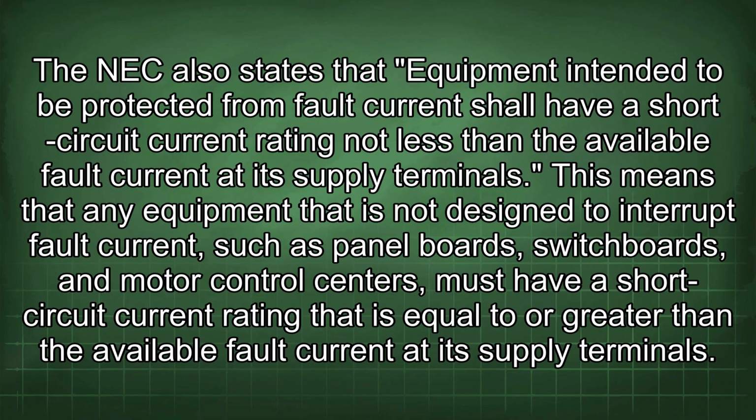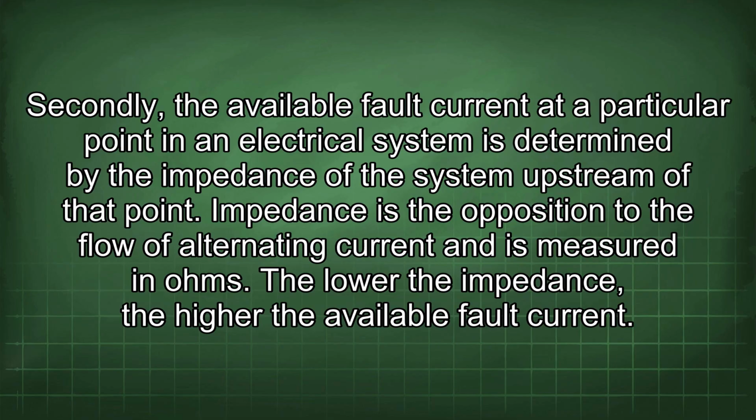This means that any equipment that is not designed to interrupt fault current, such as panel boards, switchboards, and motor control centers, must have a short circuit current rating that is equal to or greater than the available fault current at its supply terminals. Secondly, the available fault current at a particular point in an electrical system is determined by